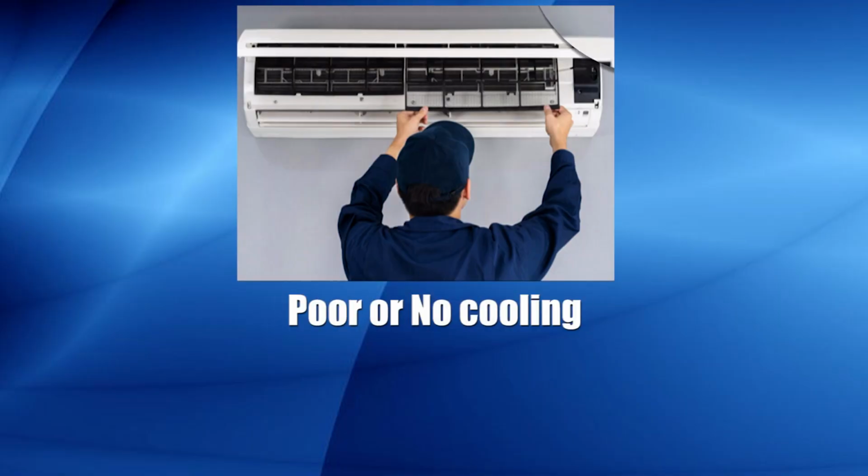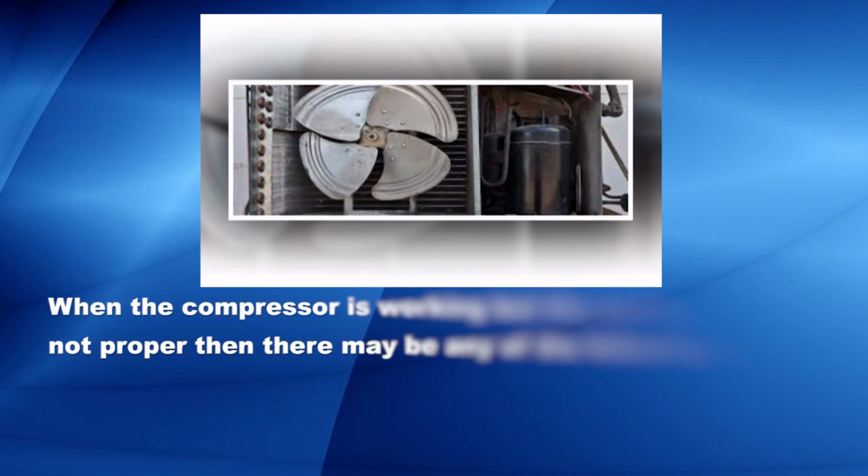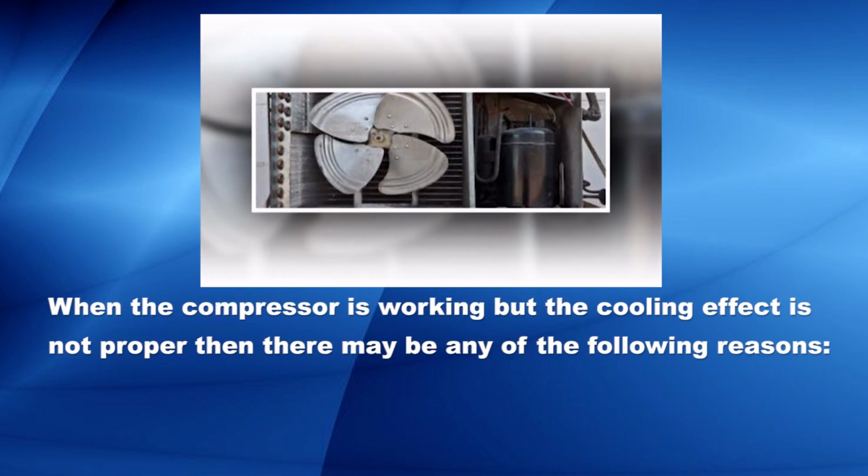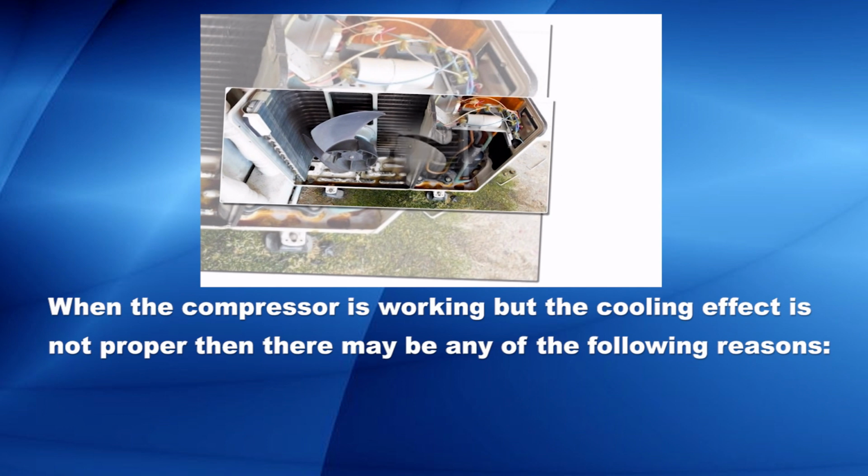Poor or no cooling. When the compressor is working but the cooling effect is not proper, then there may be any of the following reasons. Number 1, shortage of gas. If there is shortage of gas, it may either be due to insufficient charging of the refrigerant at the beginning or due to leakage in the system. It is important to inspect for any leaks. If detected, promptly repair them and replace the current refrigerant using a recovery unit.